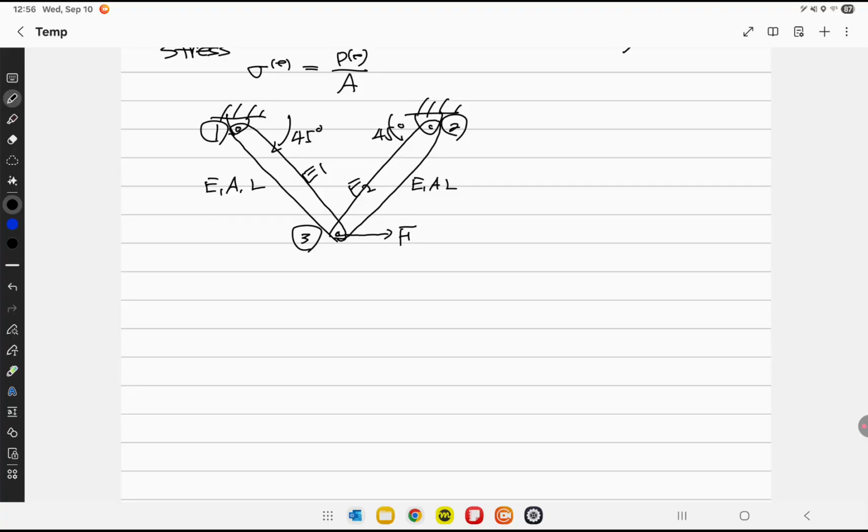Your local coordinates. Local coordinates always run from the first node to the second node. So if I choose element 1, it's connected by 1 to 3. Then you tell me what is angle phi. That again, the phi is the key point we started in class, right? Between what and what? Tell me what angle phi of that element has. Negative 45. Do you agree, negative 45?